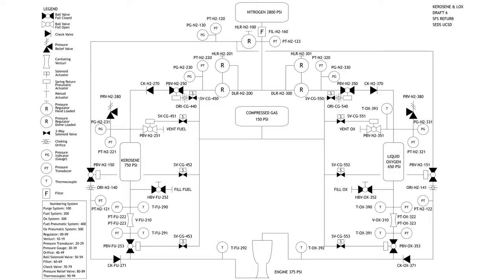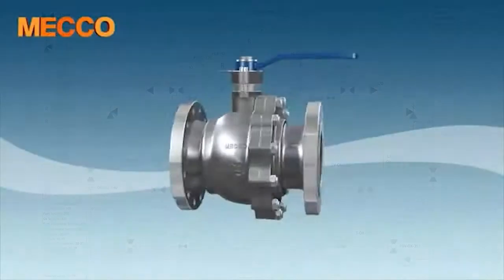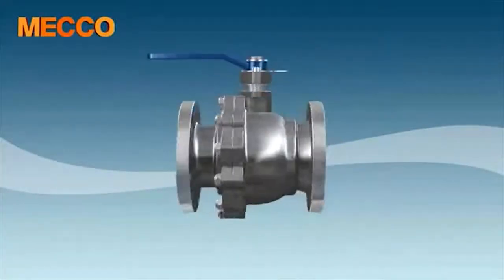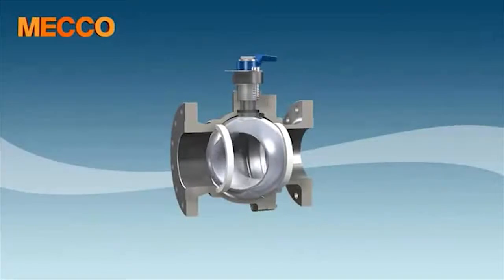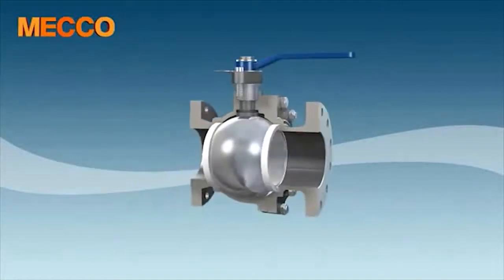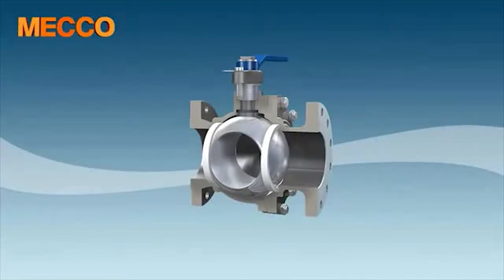A ball valve is literally, if you want to look here, and I'll show the camera in a second. Oh, nice. So this is a ball valve. It's currently closed. Inside this is a stem. This stem goes through here, and it attaches to the ball. What that stem does is you can turn this handle 90 degrees to turn the ball, and in one position no fluid will be let through. You turn the handle 90 degrees, and then fluid is allowed to pass.